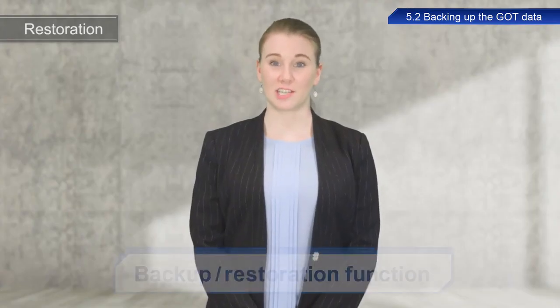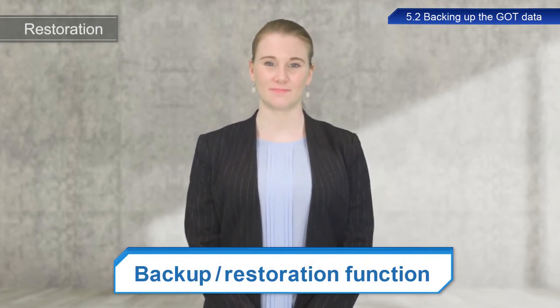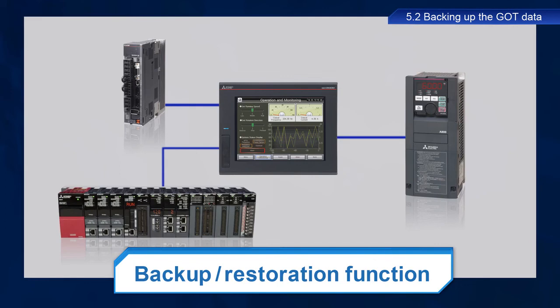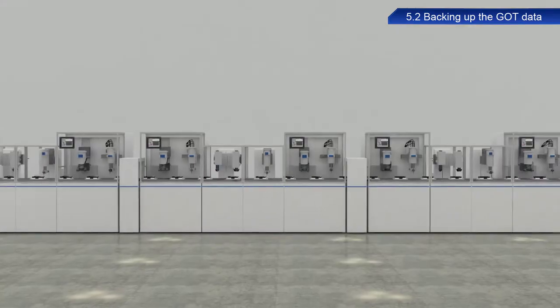There are some other GOT backup functions besides backup restoration. Data from other Mitsubishi Electric FA devices connected to the GOT can be saved to the SD card inserted in the GOT so that these devices can also be easily reconfigured using the saved configuration data when necessary. We recommend using this function to back up data if the connected device is a Mitsubishi Electric device.